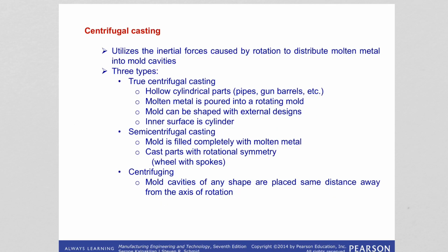So in true centrifugal casting, the molds are made of steel, iron, and graphite, and may be coated with a refractory lining to increase the mold life. Although the molten metal is uniformly distributed by the centrifugal forces, of course, due to density differences, lighter metals like impurities can collect on the inner surfaces of the casting, which can result in a change in properties throughout the thickness of the cast.